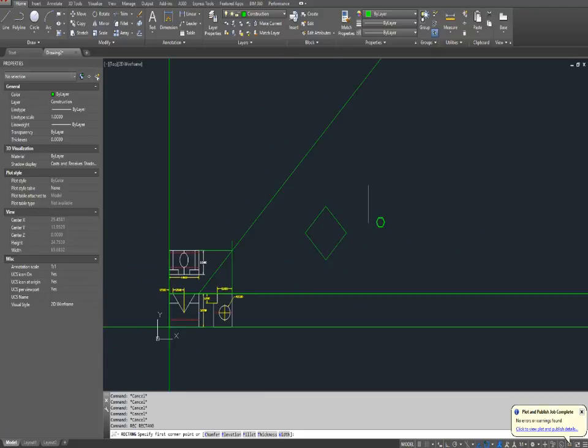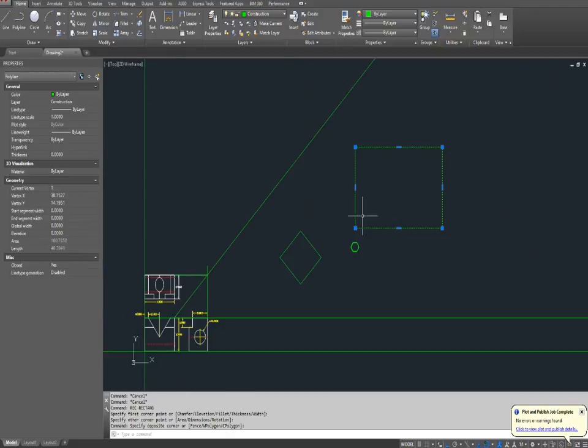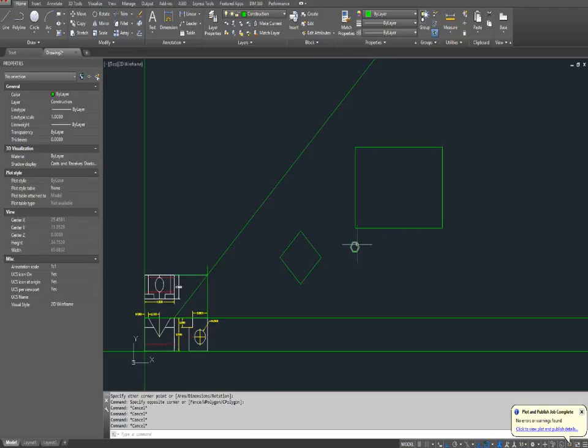there is a pretty handy function called a rectangle. So just REC, or you can get it from the pull downs on the ribbon, and you can draw a rectangle. Now it's important to note that this is a polygon. So it's a single line that runs in a circle, runs in a rectangle. So that being said, we might as well talk about polylines. And right here I have a polyline with a width set to 0.25.